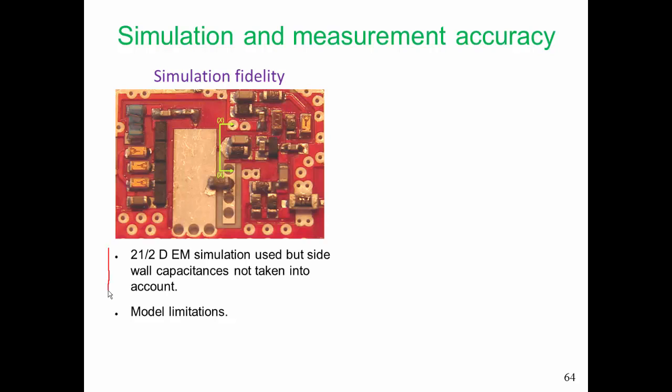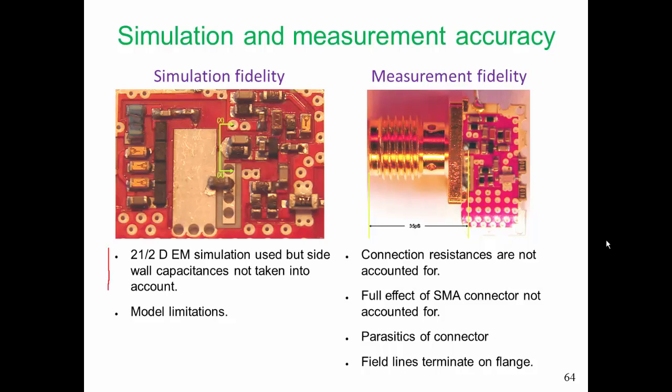We cannot get a tremendous model for the varactor diodes, or even for a fixed diode or a lumped inductor. So, because of parasitic coupling, which could be electric field-based coupling or magnetic field-based coupling, these elements affect each other. Just placing them near each other will affect components on the other side. We have limitations with our measurements as well.